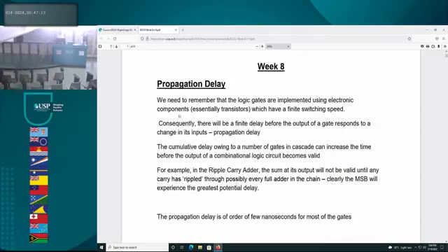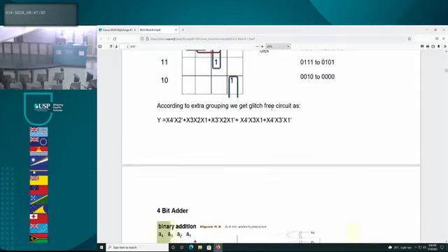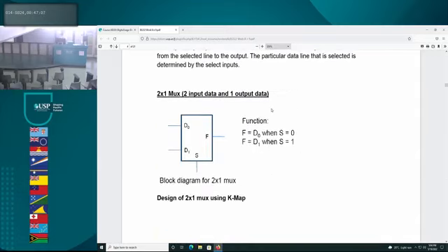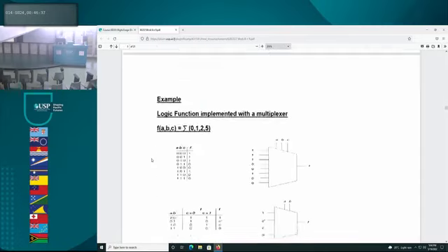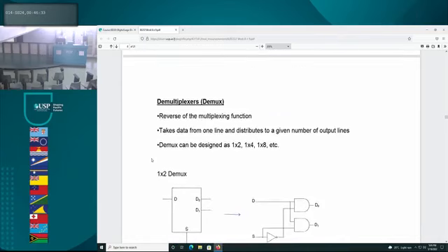All right, so we were looking at 4 particular types of devices. Firstly, we looked at the multiplexer. What is the multiplexer? There are 3 sets of lines: there is a data line, there are select lines, and then there is the output line, a single output. Using the select lines, you choose which data line gets connected to the output. Simple concept, right? For each of those, you have to know how you will derive the basic Boolean algebra.